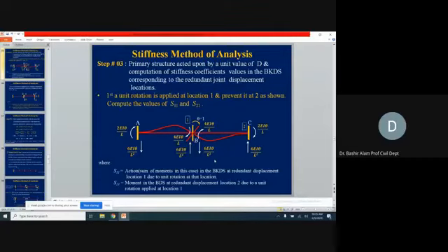Now, the corresponding actions corresponding to the D1 are which ones? These are the moments produced now at this one coordinate. And what is the moment from the left side? It is 4EIθ divided by L. And from the right side of this joint, it is 4EIθ divided by L. So we need to add them up now.